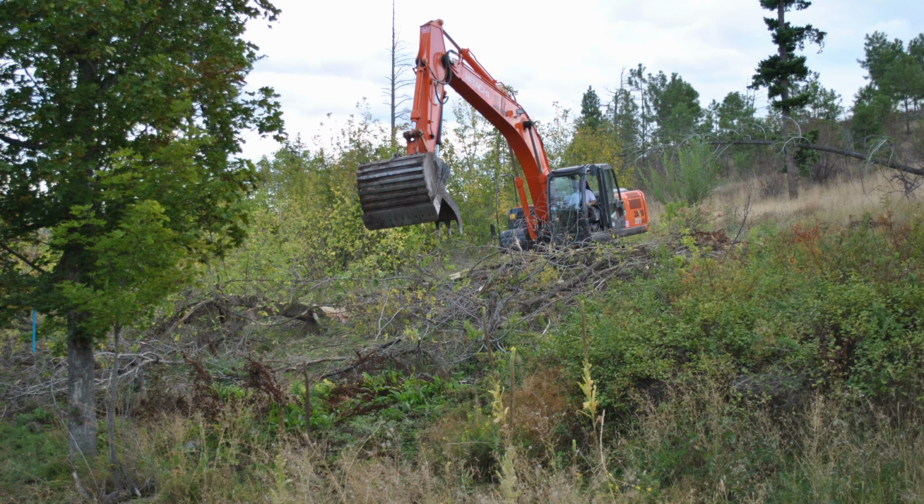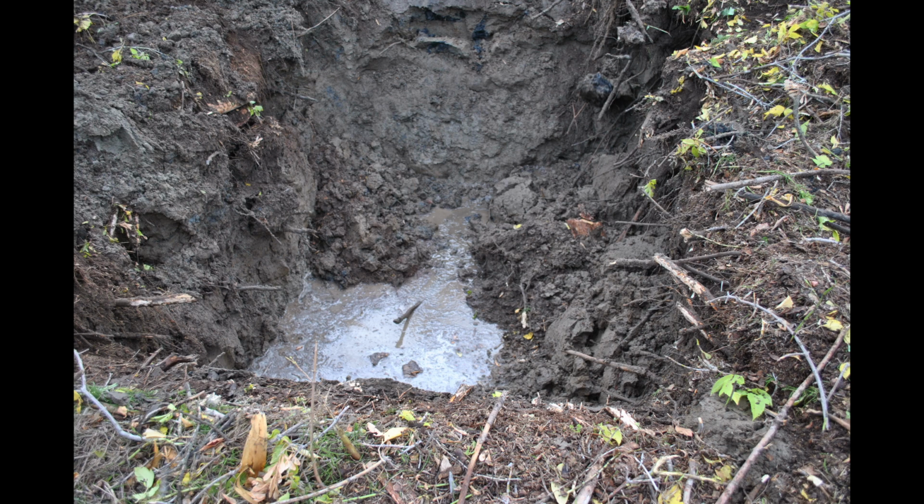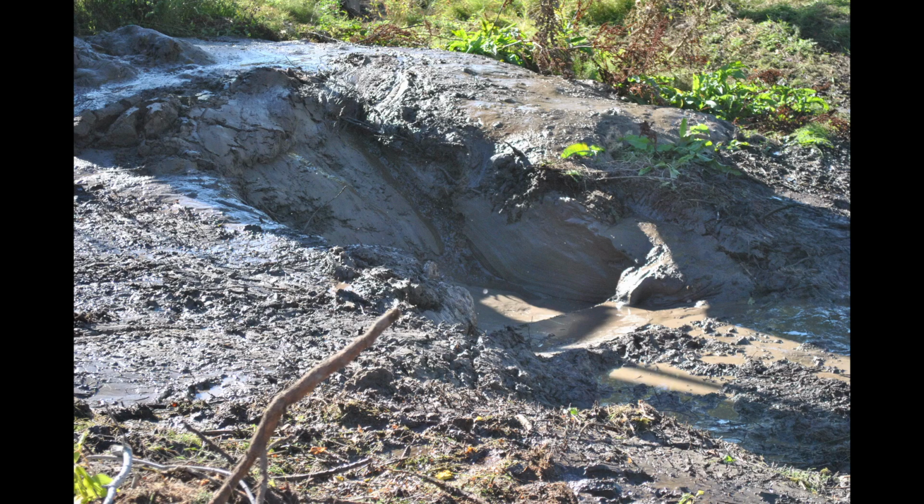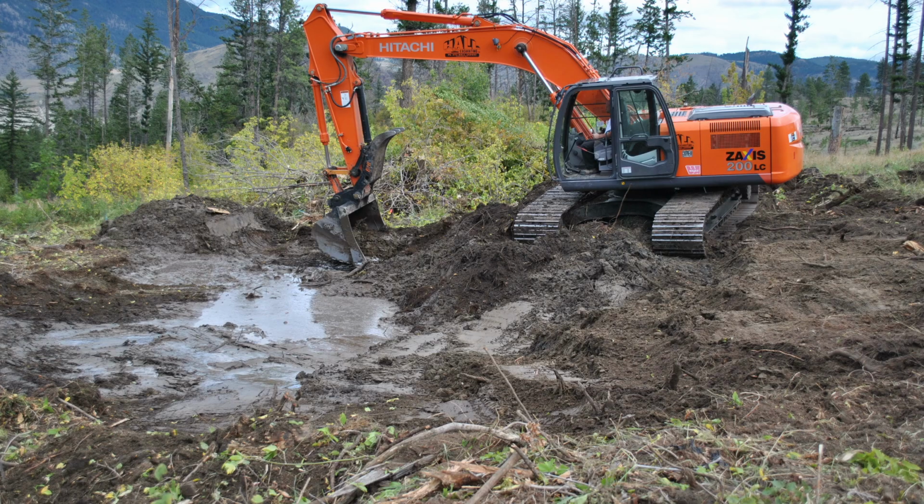The group hired Tim Hall to provide and operate the excavator that was needed to build the wetlands. We began construction by using an excavator to dig a test hole near the center of each wetland we wanted to build. The sand content increased the deeper we dug, and as we watched, water would quickly fill the holes that were dug with the excavator. We planned to build each wetland using the groundwater technique, and this technique is described in episode 13 of this How to Build a Wetland series.